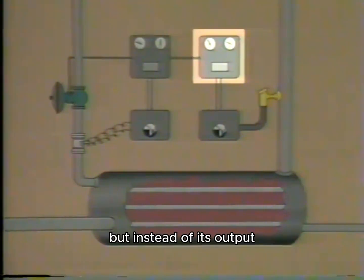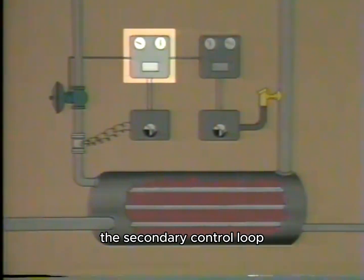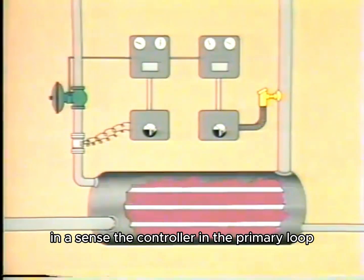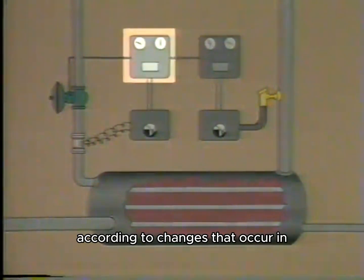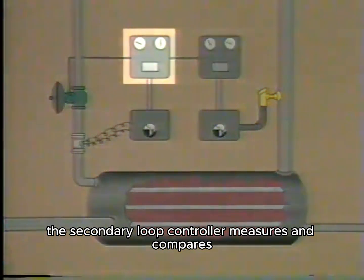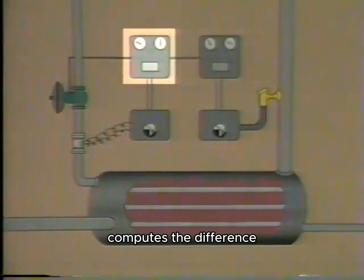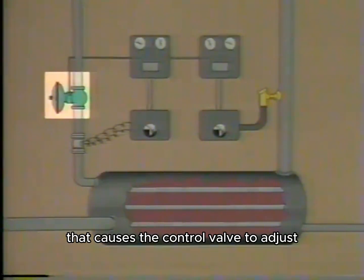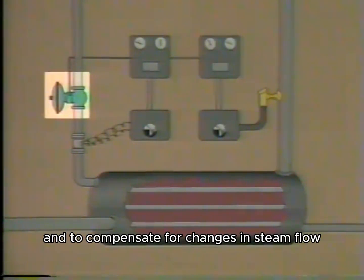But instead of its output going to a final control element, the signal is sent to the controller in the secondary control loop, where it adjusts the set point of the controller. In a sense, the controller in the primary loop adjusts the controller in the secondary loop according to changes that occur in the water temperature. The secondary loop controller measures and compares the signal representing steam flow to the new set point, computes the difference, and produces a correcting signal that causes the control valve to adjust the flow of steam enough to correct for any errors in the water temperature and to compensate for changes in steam flow.